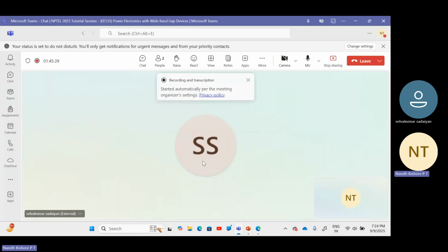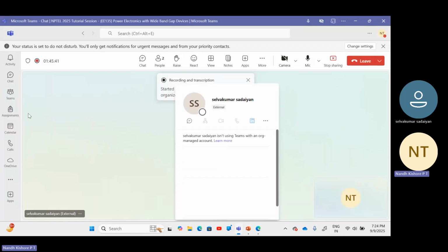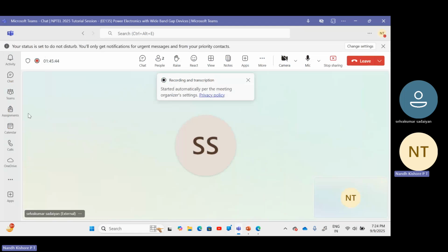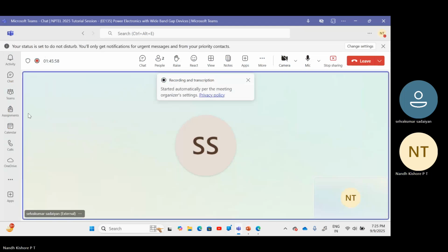I will give you the dV/dt, right? Let's say that for some application I need a very high dV/dt. Then how will I find the required value of Rg, or the required value of negative voltage, so that the device does not false trigger? That will be based on crosstalk. Those are questions we will see from next week.